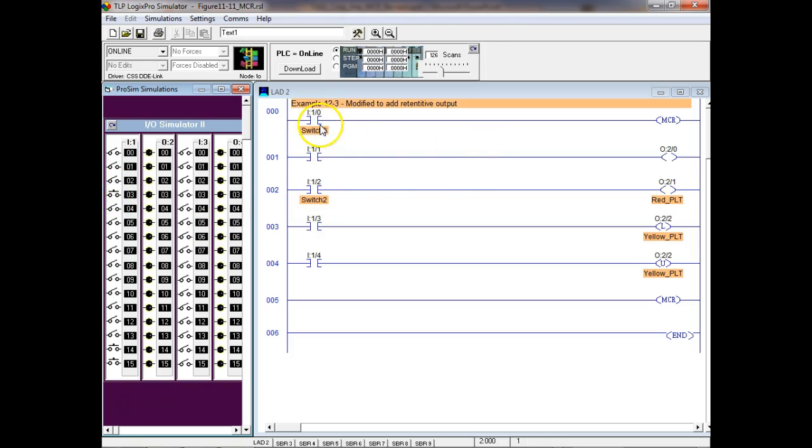So what we do is we have to make this run false up here. I'm sorry, we make it false to skip over, and then I'm going to use switch 0. Now my MCR is true. And notice what I do when I hit my latch. That output comes on and does what? Stays on, even though this run here is not true anymore, right? I understand that. So it did what? Stay latched, right? You understand that?